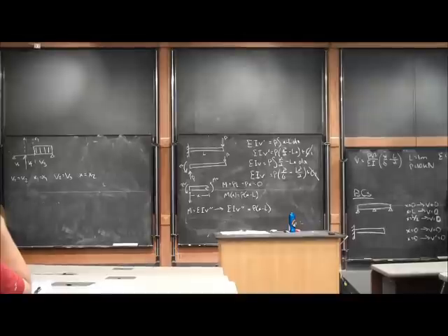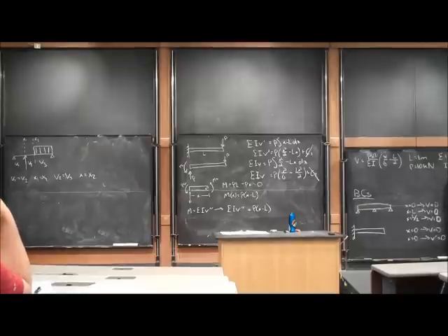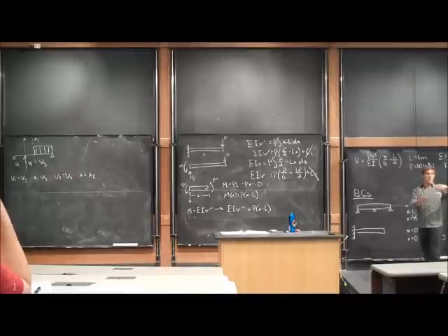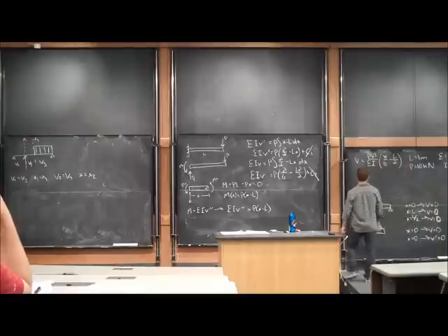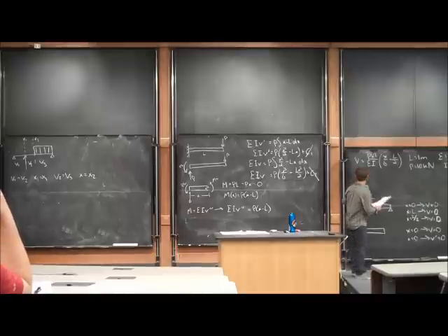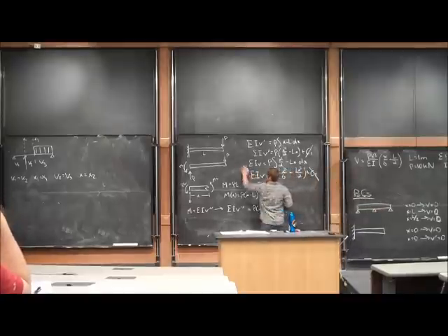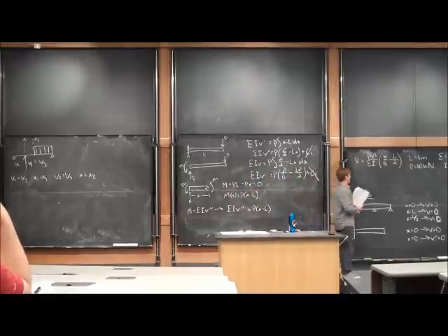And let's say that I is equal to 800 centimeters to the fourth. That's like a 7 centimeter by 7 centimeter cross section of a beam. So those are realistic numbers that maybe you would see if you were putting a load on a beam. We want to find what the deflection is at the tip, so let's see what the maximum deflection is, which will be found at the tip.